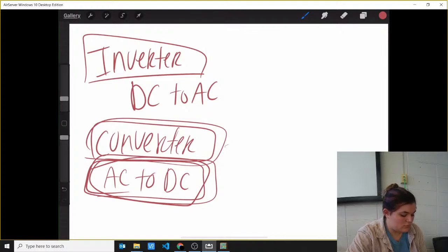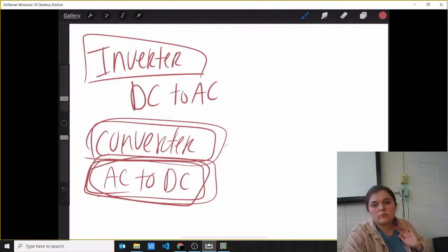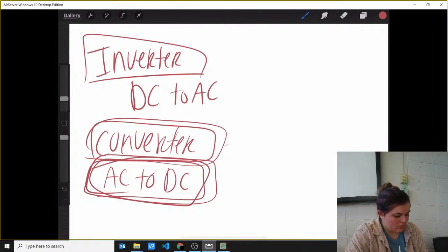So if you had a three-phase motor, you would run three-phase power to that drive. So not necessarily. Like we were talking about earlier, they're designed to operate three-phase AC motors, regardless of whether they're designed for single phase or three phase.